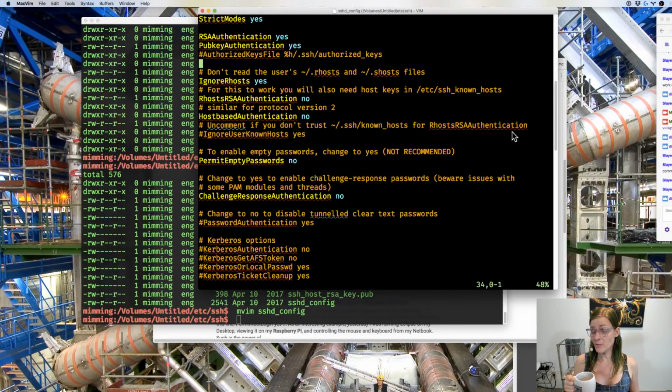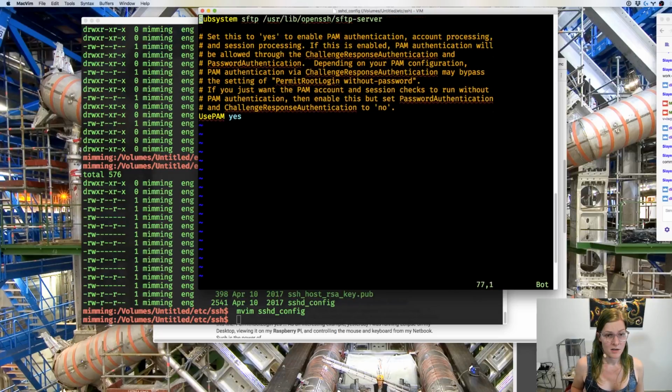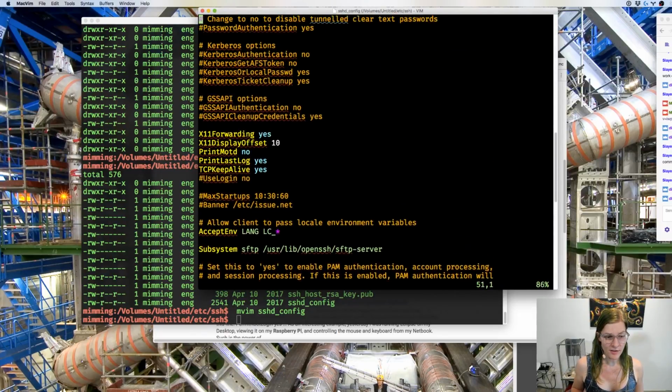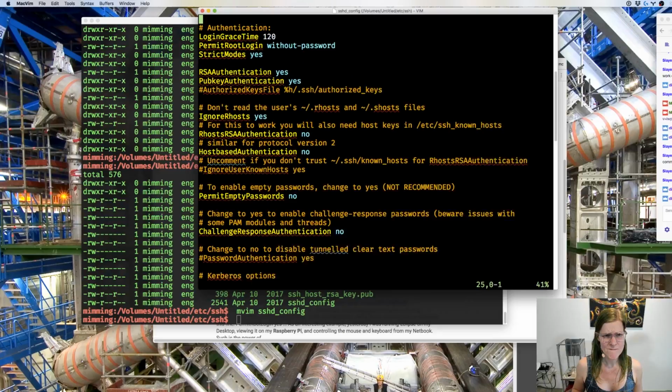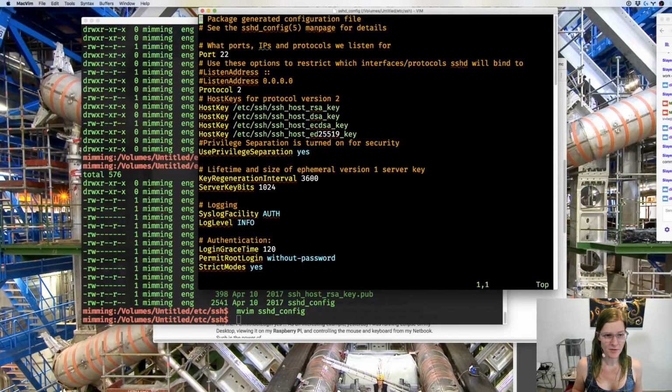Is it currently running on boot? Yes. The Raspberry Pi is starting up and it can get an IP address. But I can unplug the file system and look at it. I can just plug the SD card into my computer. So I can modify files, but I can't connect to it over the network, so I can't see the processes as they're running. So what I'm probably going to do is just reimage it, because then at least I start from a known state instead of a mystery state.